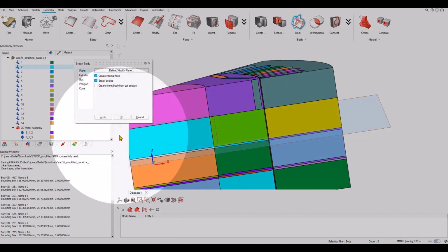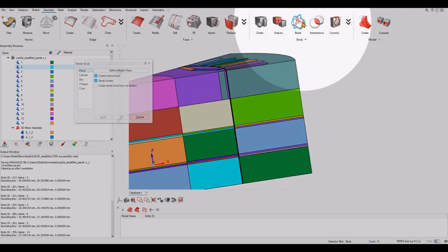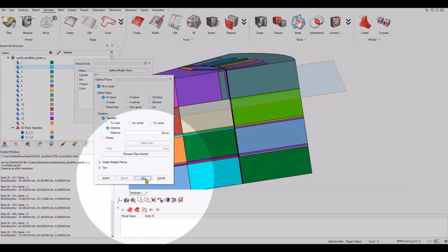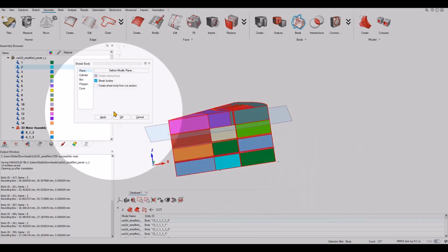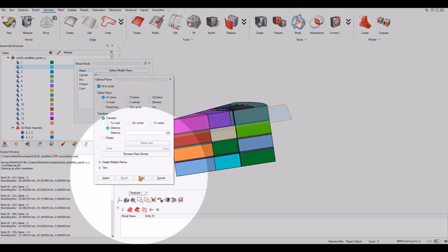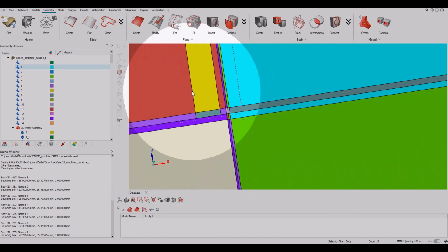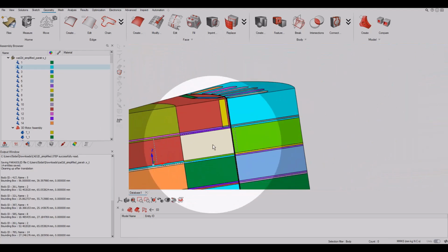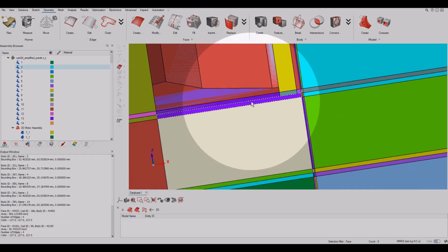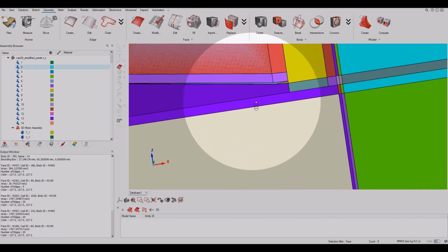So again, I cut first each layer for the stator, because the stator is extruded at one time. So I will divide it first into several layers corresponding to the step skew layers, and then I will cut the full machine on the top and bottom of each layer border to have this real junction layer between each layer. So here you can see the interest of this additional layer.